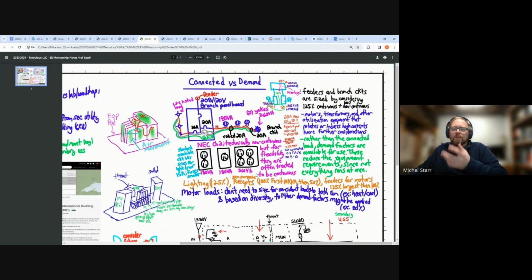So this is how the electrical code for receptacles allows you to presume load that could be anything that meets the NEMA or otherwise receptacle and plug configuration for the products that can fit in here. So there's a number of them that you can connect, for instance, to a 20 amp breaker or a 15 amp breaker based on that load.